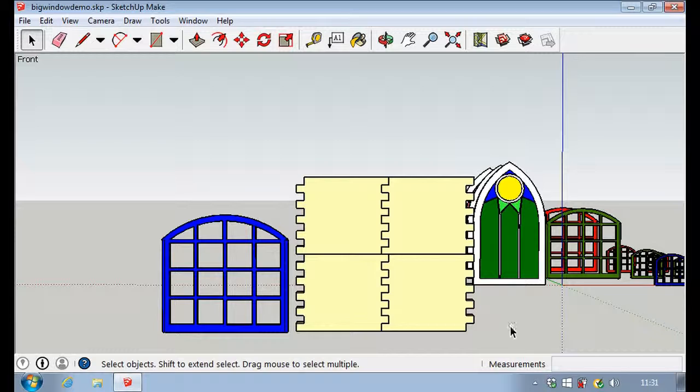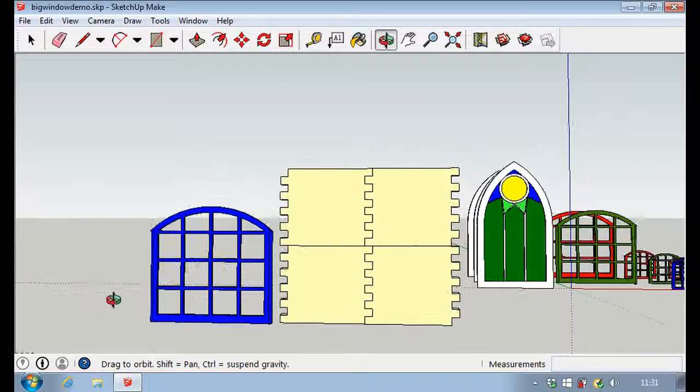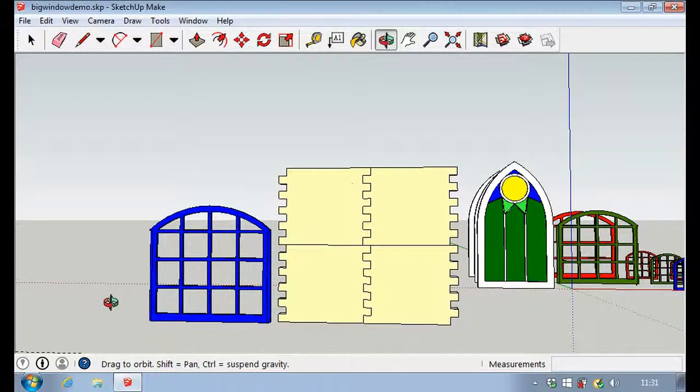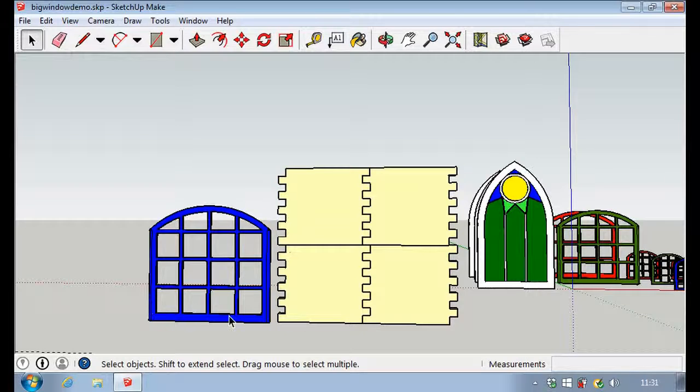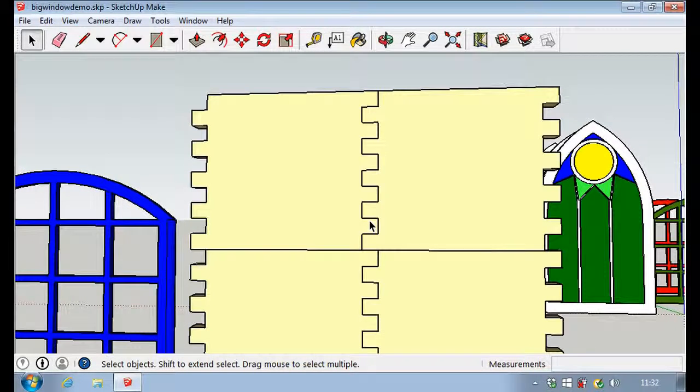The difficulty with this is that some people have said when they move it onto the face, what happens is that it disappears into the face or even goes behind the face of the model. So we're going to use a technique to try and get that window somewhere in the middle of those four building blocks. The technique that we're going to use is to grab this crossing here, this interstice, and we are going to get a piece at the back of it and put it onto that second horizontal line above the midpoint. That's the theory. Let's see if we can implement it.